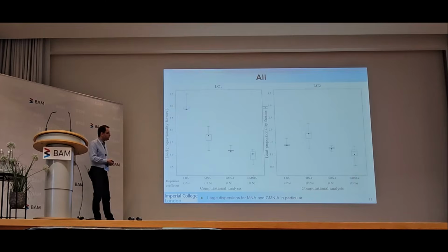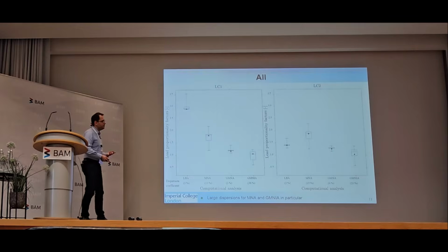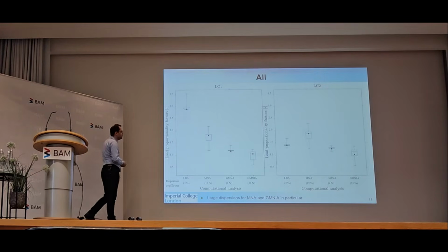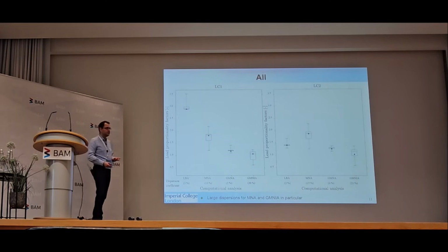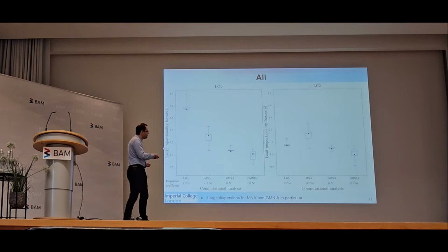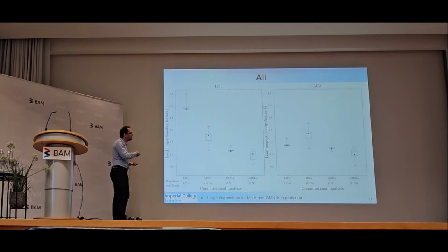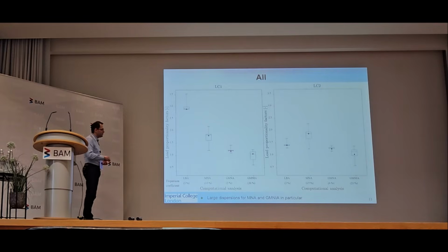I thought to comment that I think in the whole Eurocode reliability framework, there are partial factors on everything. There's a factor for uncertainty in the geometry, uncertainty in your model, uncertainty in your material, but there seems to be another source of uncertainty here, which is uncertainty in interpretation of a rule, which I think contributes to quite a bit of what is seen here. And I think this is quite remarkable and actually a little alarming to me.